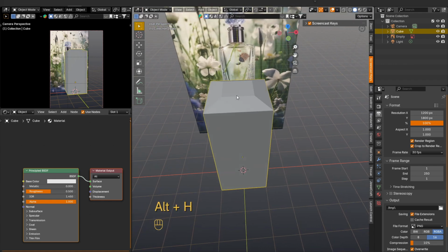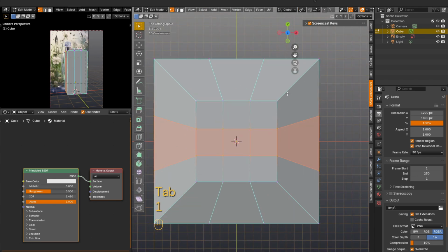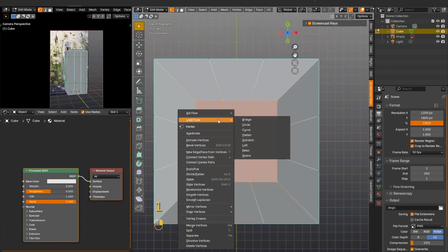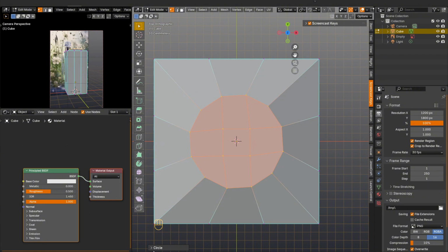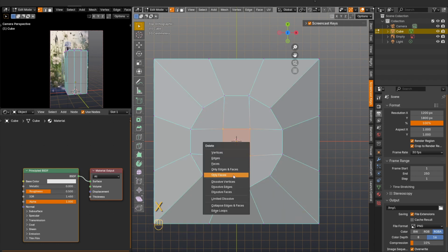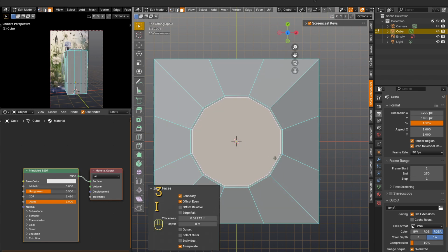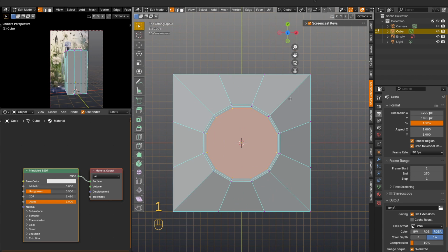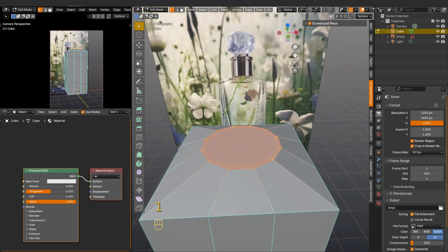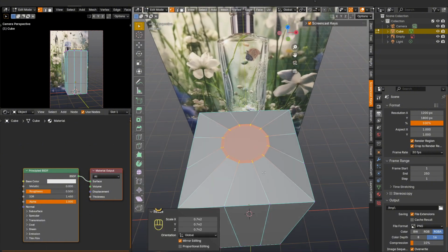Now press the number 7 on the numpad and go to the top view, select the vertices that we got and apply to them Add-on Loop Tools and immediately go to the small menu on the left below to slightly correct the degrees. Now we need to dissolve the 4 vertices that are in the center, which gives us the opportunity to use insert, do it twice. We need to make sure that we have the desired diameter of the neck of the bottle. Delete the round central face.